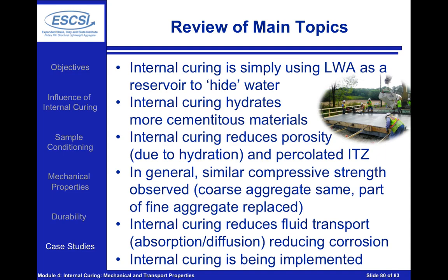Internal curing is going to reduce fluid transport. This will be reducing absorption. This will be reducing diffusion. This will lead to reductions in the ions entering the system and causing corrosion. So this will delay the time to corrosion and will increase the overall service life of our concrete.